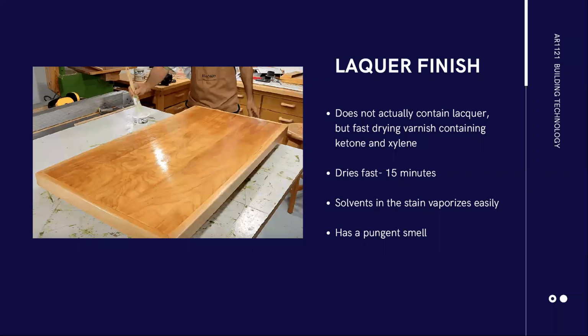Next is lacquer finish. It does not actually contain lacquer, but is a fast varnish containing ketone and xylene. These stains dry fast, with a curing duration of just 15 minutes, and the solvents of lacquer finish vaporize easily and have a huge pungent smell. So if you use lacquer finish, you have to wear a mask because the smell is strong.